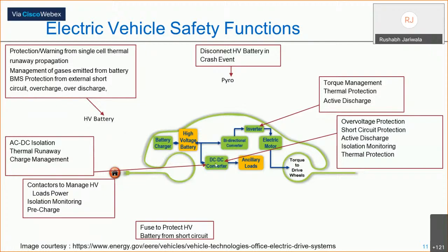DC to DC means the isolation between the HV DC and the LVDC, because that is something important. And then another thing is during the charging process, the DC-DC conversion process, its power electronics should not lead to a thermal runaway kind of event. And for that, one needs to design the cooling channels and all that in the right way.